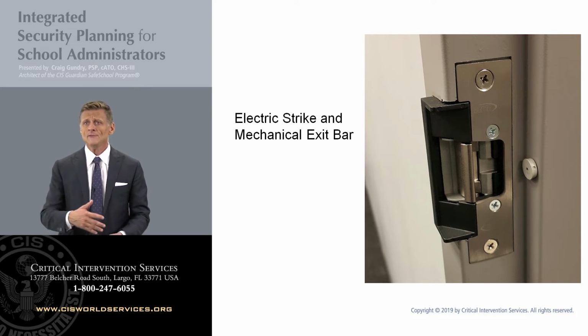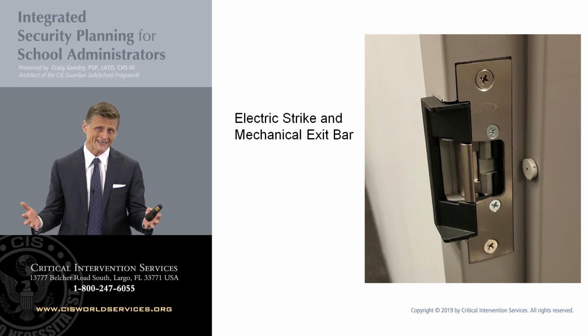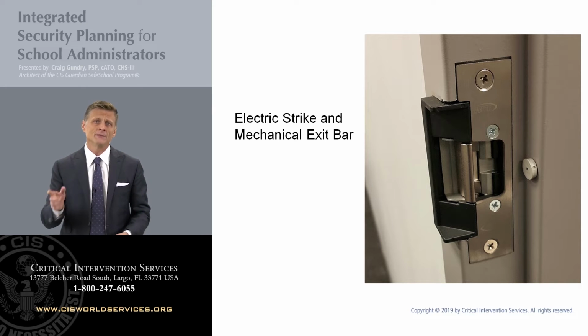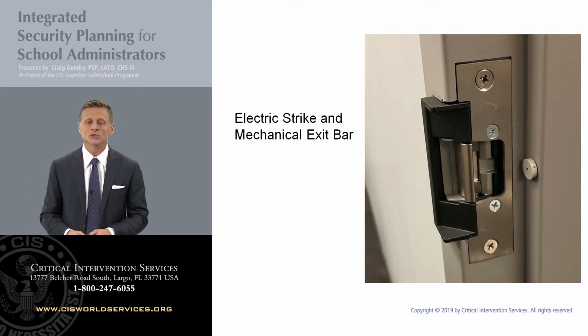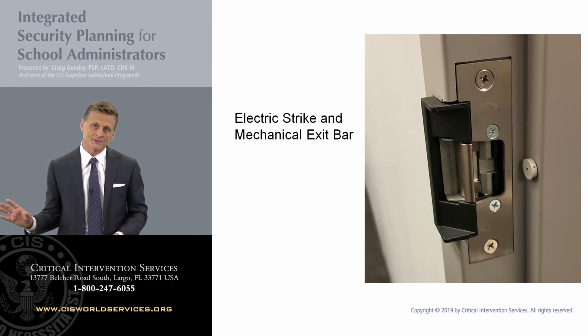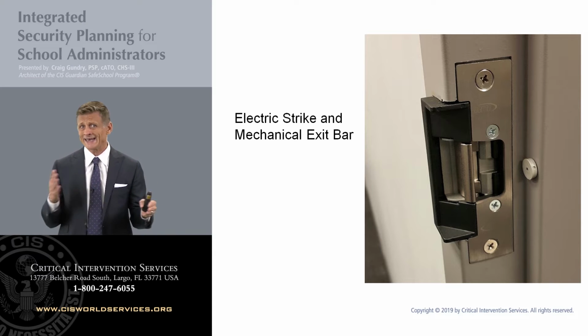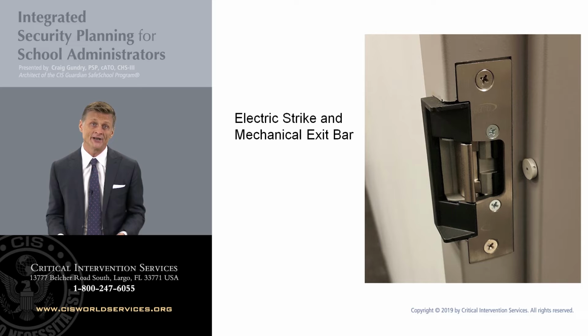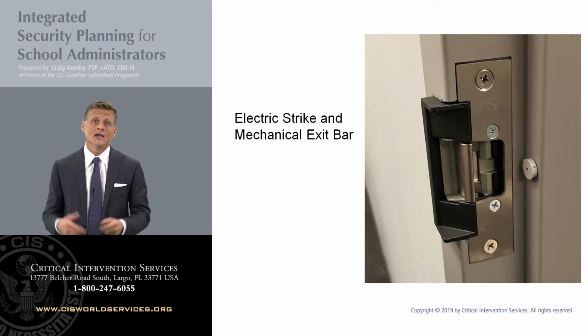CPNI in the United Kingdom, who studies physical security design and hardware, that's basically their critical infrastructure security organization at the national level, looked at the vulnerability of these different types of locking systems and determined that electrified strikes were very vulnerable to prying and forced entry by prying. Now, truthfully, in an active shooter event, it is unlikely we're going to have a bad guy show up with a pry bar. So in that case, even using an electrified strike should still provide us with a very good level of intrusion resistance against simply a gunman using impact force for entry.